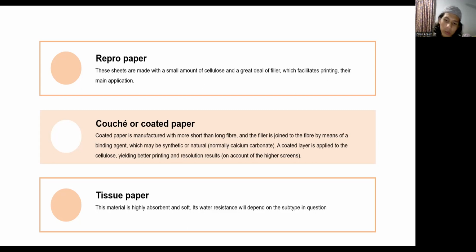One of the most common options for coated paper is white coated paper, because if the coating cracks, the background color is not apparent, although the color difference will be noticeable in colored coating. There is also the matte or semi-matte finish, also involving the application of surface ink, although in this case it will be less shiny. In terms of strength, because of the high amount of filler and short fiber, it is quite low as opposed to the high printing quality.